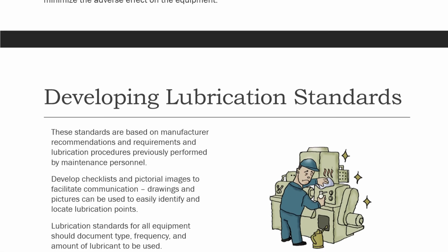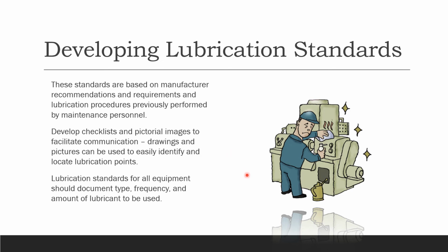Developing lubrication standards. These standards are based on manufacturer recommendations and requirements and lubrication procedures previously performed by the maintenance personnel. That's how we develop the lubrication standards. Develop checklists; pictorial images are so important to facilitate communication. Drawings and pictures can be used to easily identify and locate the lubrication points.